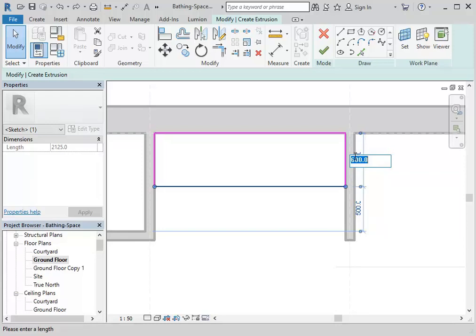And then also, we've got to set out for the kickboard. Underneath the kickboard, of course, being room for your feet, that's going to be set back behind the cupboard doors. So that'll be another 50 mil. So here, I'm making the kickboard. I just want to explain, that's why I'm making this 550. That's going to be my kickboard depth, and then when I do the cupboard doors, I'll make them 600.